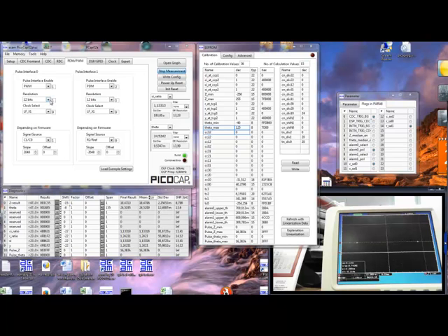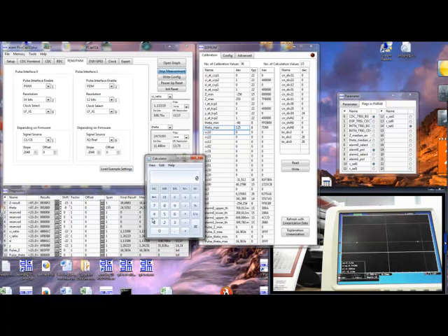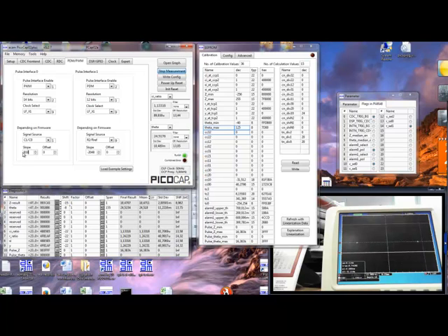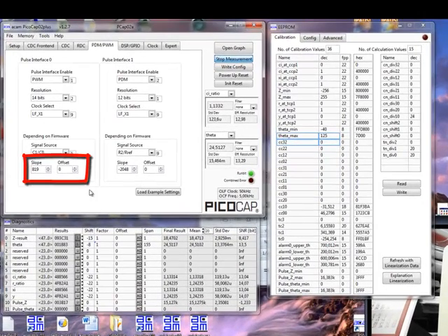After that basic settings, I can now configure the PWM output to my requirements. I select, for example, 14 bits for the output and will now calculate the slope and offset parameters I want to fill in here. So 14 bits corresponds to 16,384 steps, and I divide that by 20 psi, which is the range I formally configured between 5 and 25 psi, if you remember. And this gives me my slope of 819, which I fill into this field.